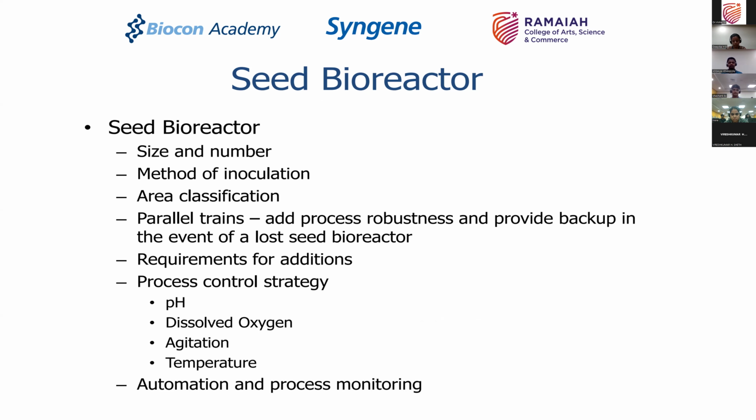What is the area classification you need? Do you need an area to be classified as grade D, grade B, grade C, or can you do it in controlled but unclassified areas? Very large fermenters are generally run in ventilated areas. If you walk around large manufacturing facilities which have 100,000 liter fermenters, 60,000 liter fermenters, these are generally not classified areas. Okay, parallel trains only to provide backup if you lost a seed bioreactor. I told you about it. Requirement for addition.